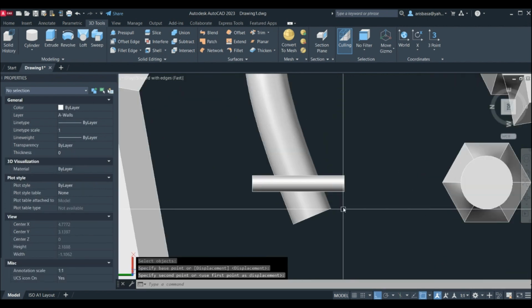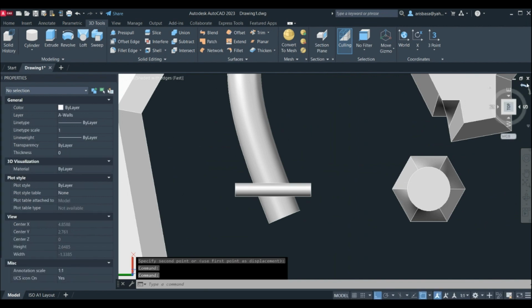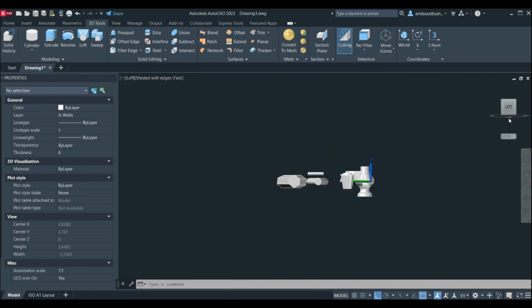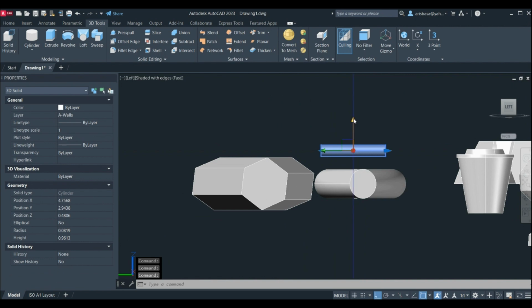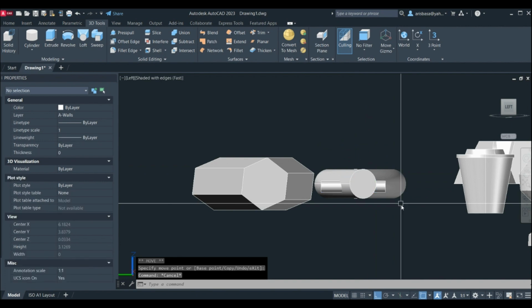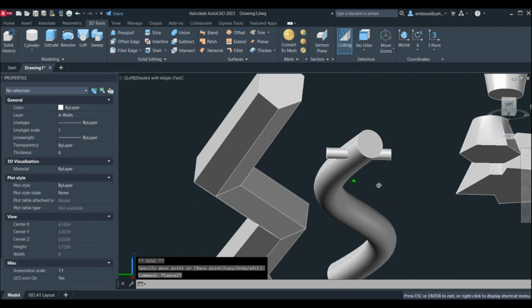So if you want to cut that hole, you have to make sure that it is intersecting that line. So maybe we use this view. So it's above, right? If you select that, you can easily bring it down by clicking on this arrowhead. Just wait until it changes color and you have that blue line, and then click it down so that you can bring it right there. When you reach the place that you want, then it's okay now.